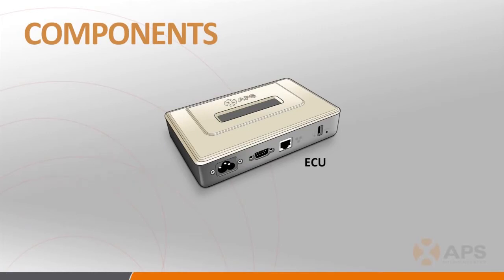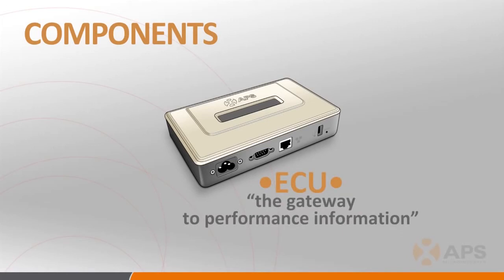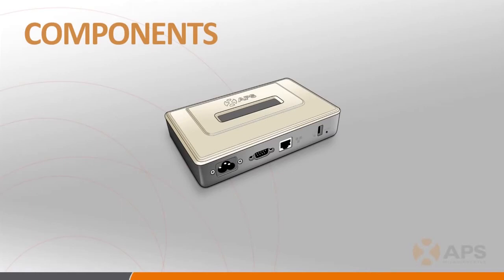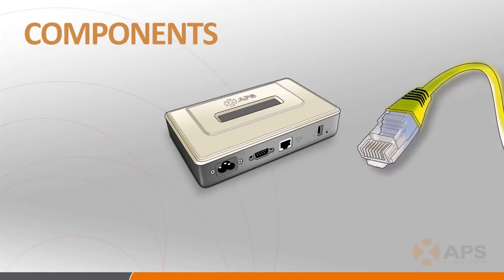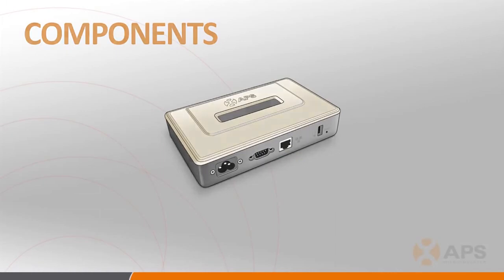The ECU, while optional, is an essential component of the remote monitoring system that should be thought of as the gateway to the performance information that can be retrieved from each inverter and its assigned PV modules. Again, the ECU uses the PLC protocol to communicate with each of the inverters. Please note that the ECU is not a wireless device and requires an electronic bridge or direct Cat5 connection to communicate to a network router.